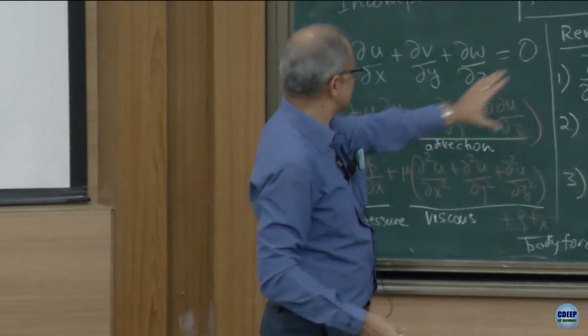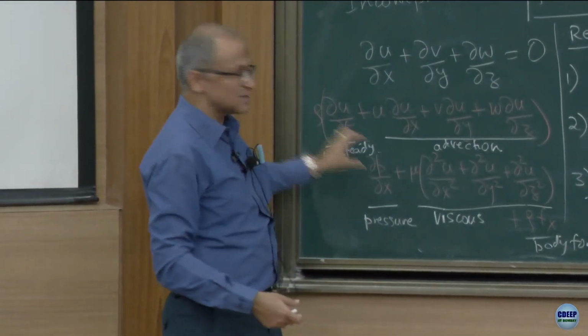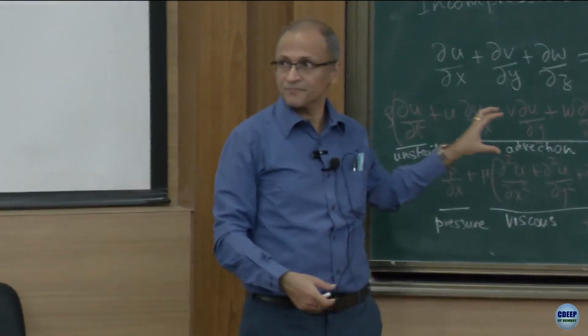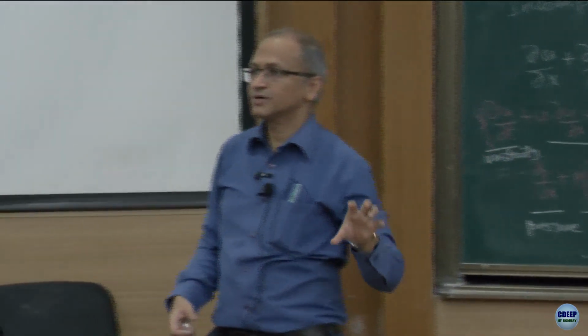But how do the absolute values come into the picture? Maybe through the properties themselves. Will my viscosity be different at these two values? Will my density be different at these two values of pressure? If they are, then those constants which we are not talking about, sitting as constants in our equation, would have different values. That's how pressure comes in an indirect way. It affects our solution, but not in a direct way.